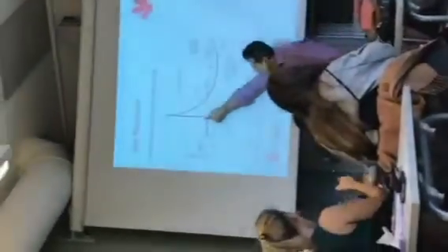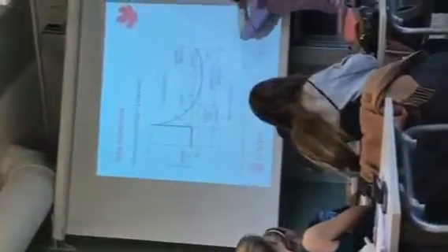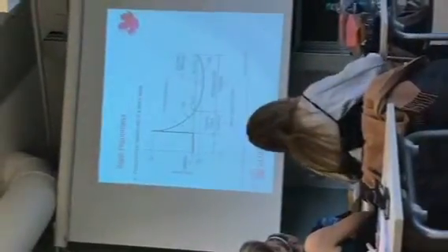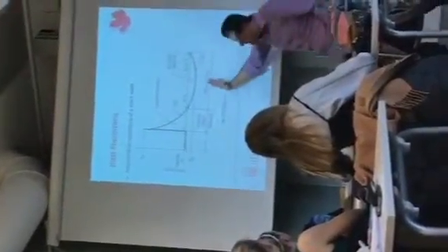Okay, so let's look at how a blast actually looks. You have this initial spike in energy, but then what happens after that? So imagine this is the front. This is the front that actually hits the item. Could be a column, could be a wall. And then you have what we call a positive phase. This exponential function is typically represented as a triangle.